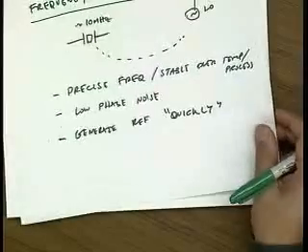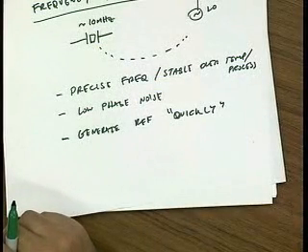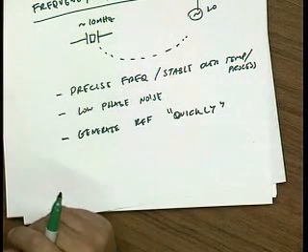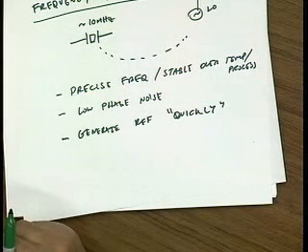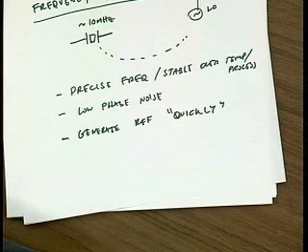Yes? Does the high impedance of MEMS resonators hurt their application for oscillators? Not for oscillators, no. It hurts them when you try to use them as filters, but for oscillators it actually helps.